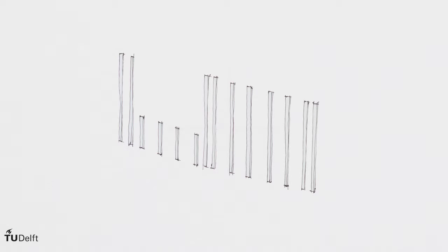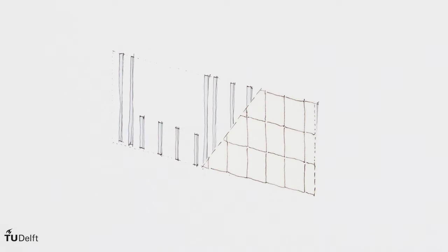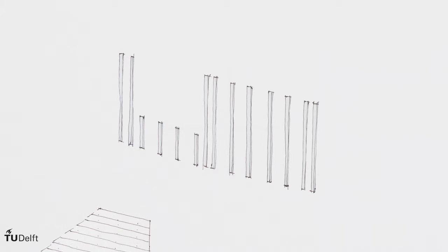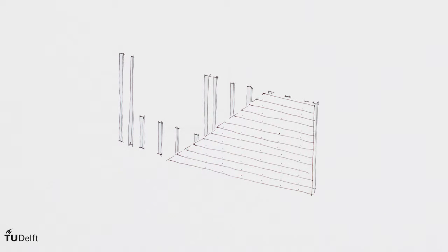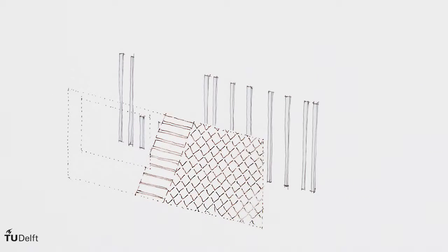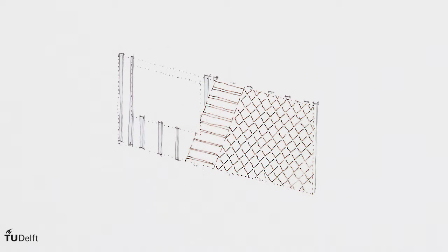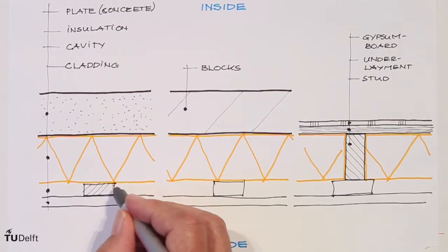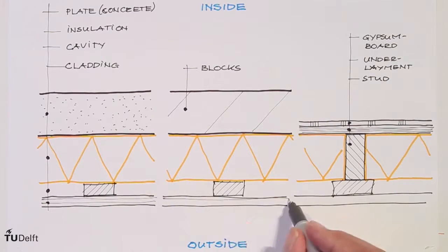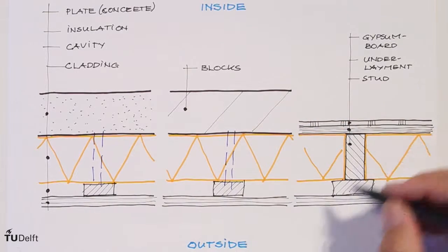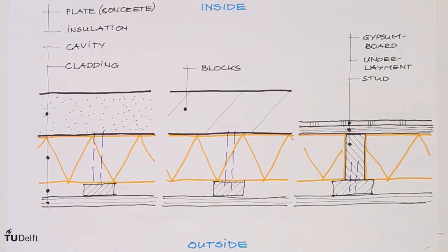The last type of rain screen shows by all means the widest range of variations. Here, thin plates, planks, boards, shingles of wood, metal, stone, glass or plastic in a wide range of dimensions are fixed on a system of rails or laths, which in its turn is connected through the thermal insulation with the inner leaf. In the case the inner leaf is a system of vertical studs, the anchors between the inner and outer leaves should coincide with the posts in the element.